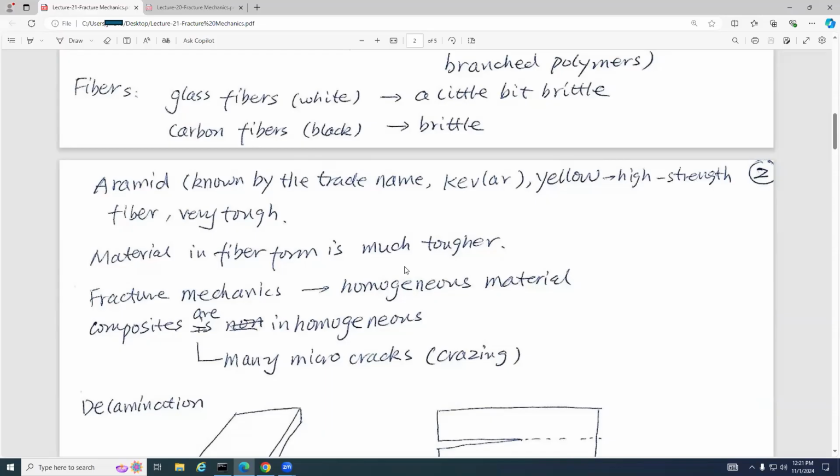So isotropic means that for one location, for any generic location, the mechanical properties are the same in all directions. Okay? Isotropic and homogeneous look very much the same, but they are different. Isotropic talks about orientation at one point, while homogeneous is talking about location, different locations. So usually for simplicity, when we talk about this series, we talk about homogeneous and isotropic material.